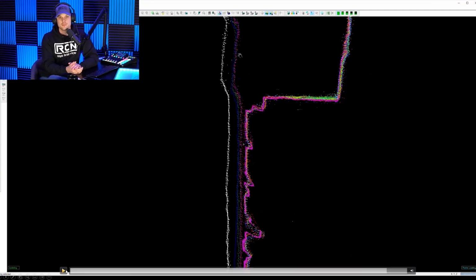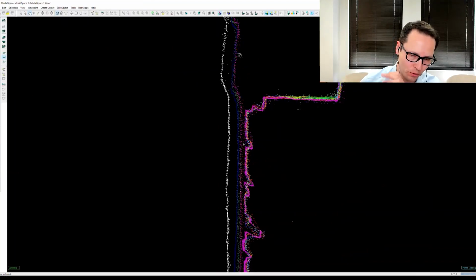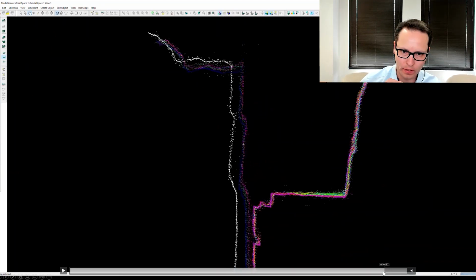Yeah, and the other thing is, when you draw this, if you do have to use the Matterport data to create an elevation view, for instance, if we look at this fascia right here, this is a wood profile, or we have the soffit. Which one of these lines is the actual elevation? We don't know, right? So you will have to introduce some error, and you need to understand what that error is. Is it going to meet the level of accuracy specifications published by the USIBD? You might say, okay, the measured accuracy is X and the represented accuracy is Y.